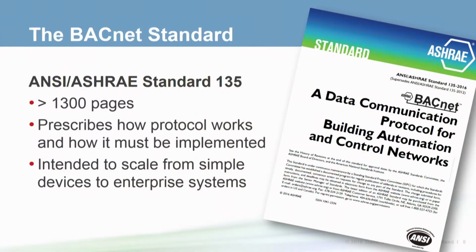So a vendor can decide what functionality to include in their products. The set of features they choose to implement will change based on the intended use of the device. It's important to remember that no device implements all the features of BACnet. The functionality needed to implement the temperature sensor is much less than the functionality needed for a building controller. The BACnet standard was never intended to be a guide for engineers on how to specify an automation system. So the responsibility falls on the specifying engineer to know enough about the functionality of BACnet and how the protocol is intended to be used so that you can correctly specify a system.